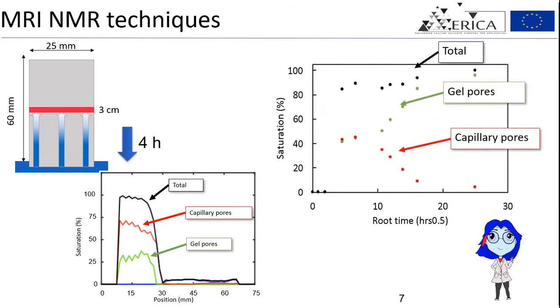We observe that a large amount of pores in red decrease after a few days of wetting, while smaller pores in green increase. This is called pore relaxation and is observed in samples where gel porosity is removed while drying. After 1 month of water ingress and pore relaxation, we observe only gel porosity. This indicates that initially larger pores are filled and then diffusion to smaller pores occurs.